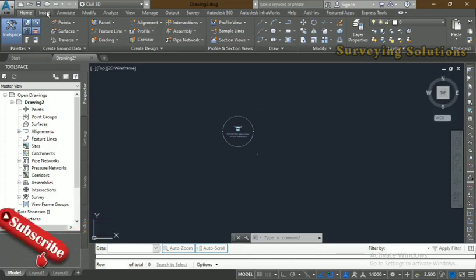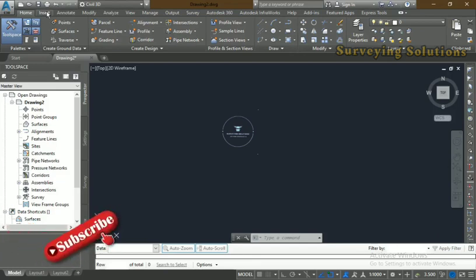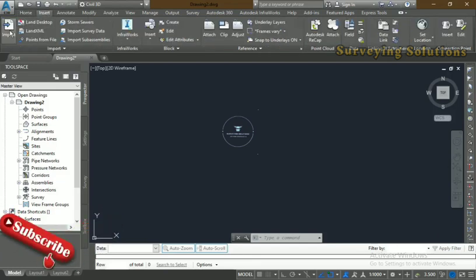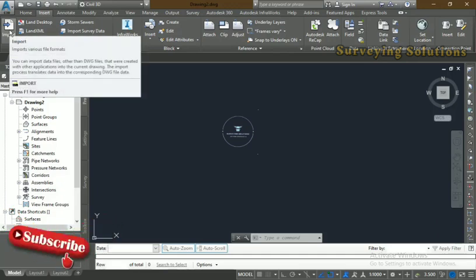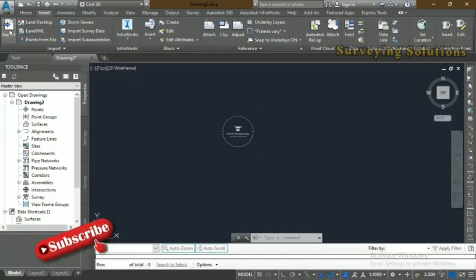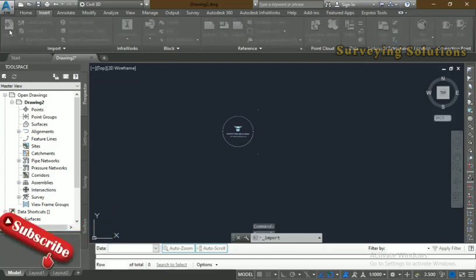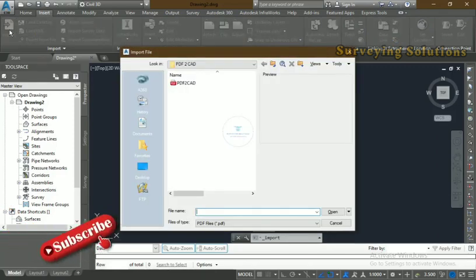So we have Insert here. Upon clicking on it, it takes you to this next interface where you can import various file formats. You can import data files other than DWG files that were created with other applications into the current drawing. So we import. It will take us to the file directory where we might have saved, or kept, the PDF. We actually saved ours in a folder called PDF to CAD, so we have a file there.